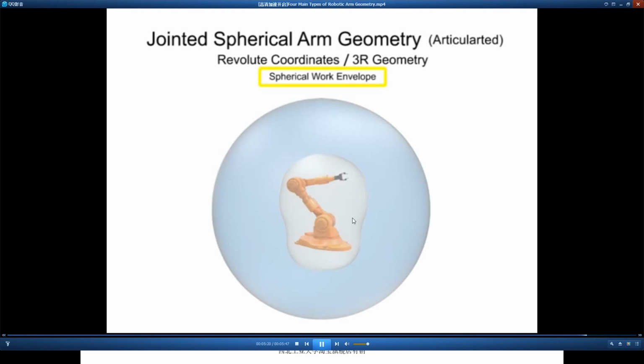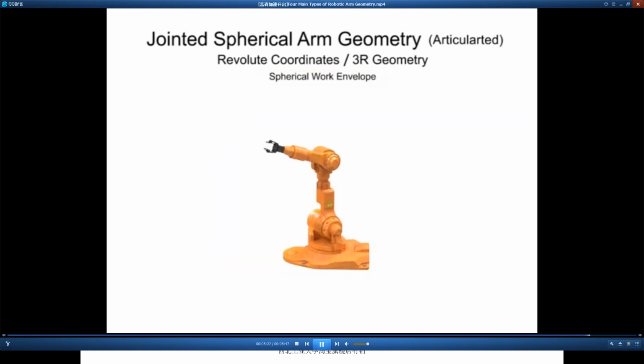The advantages of this type of work envelope is a robotic arm with very deep reach, minimal floor space use, and high positioning mobility of the tool end arm. Due to its mechanical complexity and the complexity of its controller, this robotic arm typically comes with a higher hardware cost and requires skilled technicians.